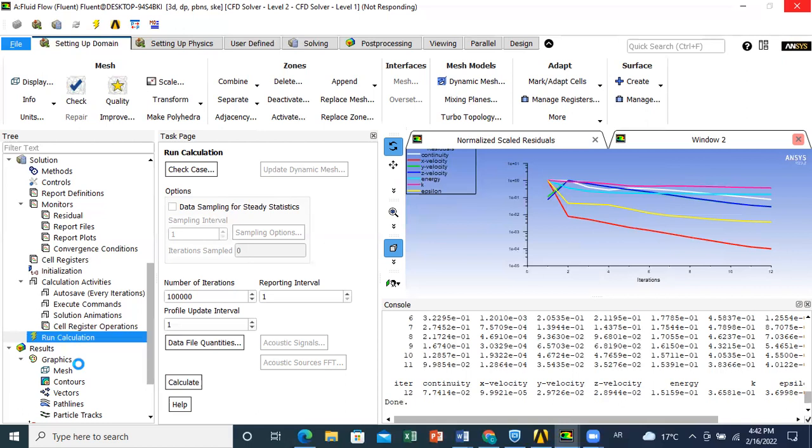You should wait for a number of iterations that is high enough to have a decrease of your residuals. Whenever you have reached a nearly convergent state of your residuals, you can stop from time to time. Even if you didn't reach the residuals you selected, like 10 minus 6, for example, if you reach 10 minus 4, you can say, let me check if these residuals will give me a good result. So I can stop before the criteria I put for convergence. I explore my results and see if they are physical.